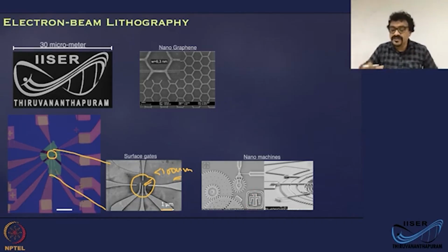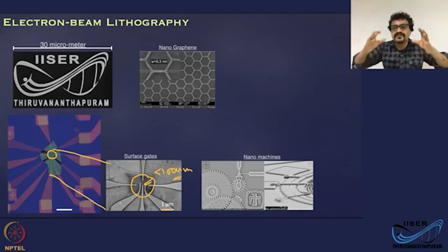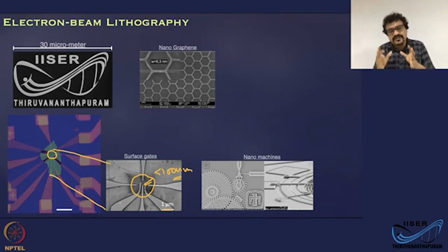So this slide tells you how powerful electron beam lithography is, but the downside is that the substrate choices are limited and the throughput is really low because this is serial processing. You have to write structure by structure. You cannot expose the features across the complete wafer at once. It is a writing process, whereas the other one is an exposing process: you have a mask and you expose all the regions at once. Here you write the features one by one. So this is not really compatible with ultra high throughput processes. You don't have as much yield as the photolithography process.